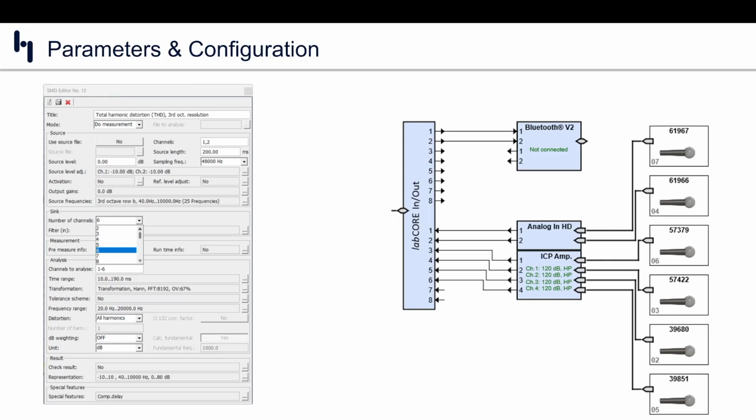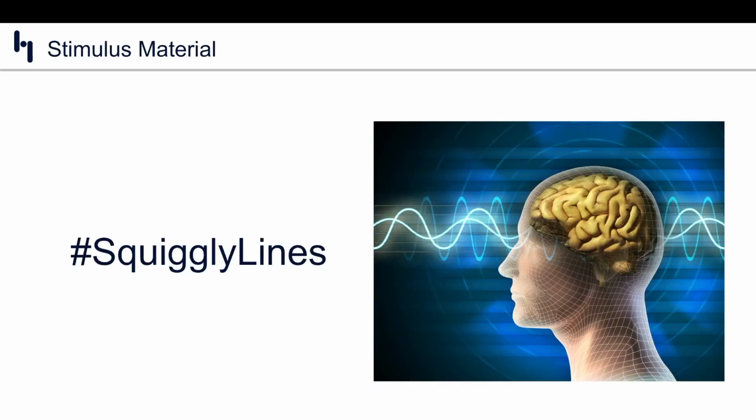Generally, ICP mics are going to be the easiest to work with due to the cabling only needing to be a 2-wire construction as opposed to the thicker and heavier 7-wire construction found in LEMO. We strongly recommend 1/4-inch microphones for this type of work since we're working with potentially diffuse sound fields and wanting to capture sound up to 20 kHz. The 1/4-inch mics are smaller than 1/2-inch mics and therefore have less influence on the sound field they're in.